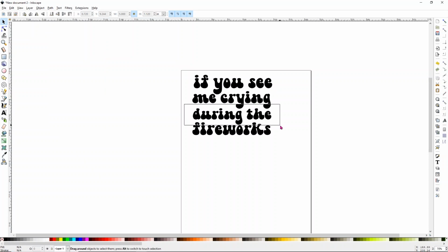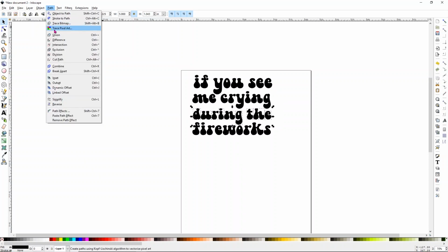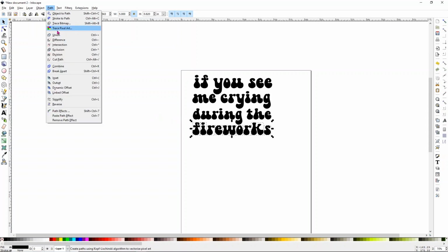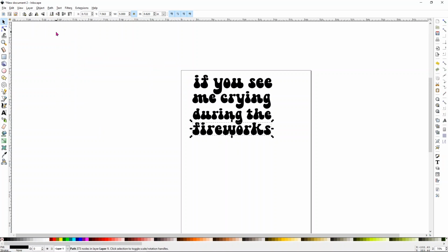We're going to select the whole line, go to Path, Union. You can also use one of the shortcuts that I never use. I think, let's see what it says it is. Union is Control plus. I don't like to do that. That's just a me thing.